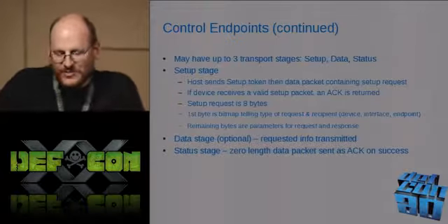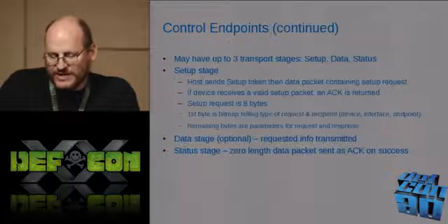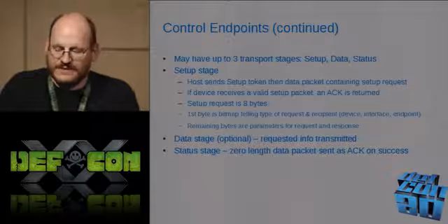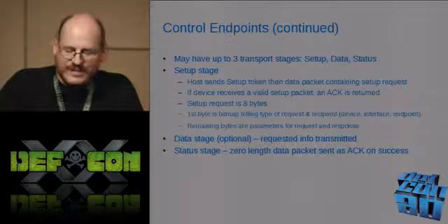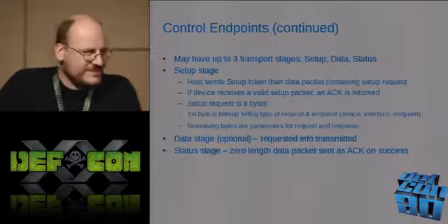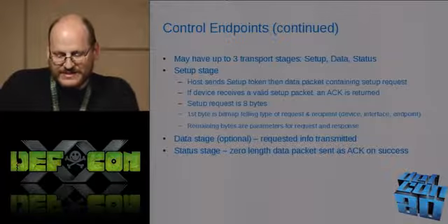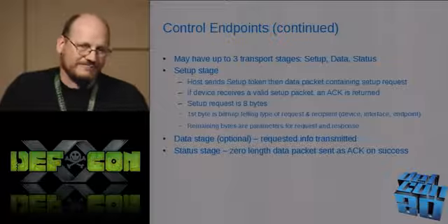All right, control endpoints. You got 3 stages in a control endpoint transfer. You have a setup stage. Hey, let's talk. Maybe a data stage, depending on the kind of communication, and then a status. All right, so the status stage, you just send a zero length packet back that says ACK. Yeah, we're all good.